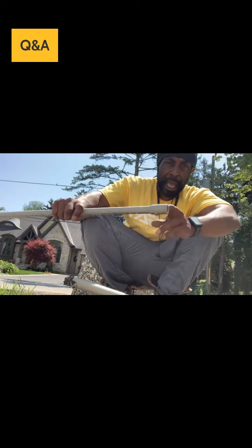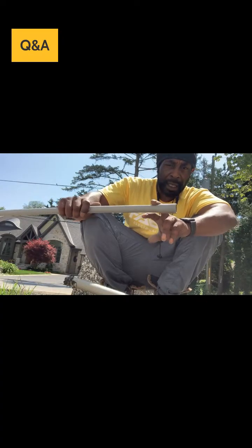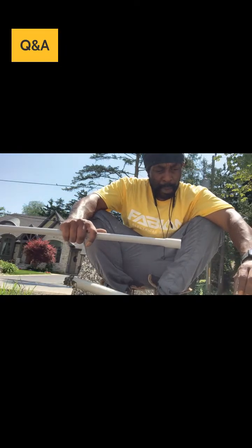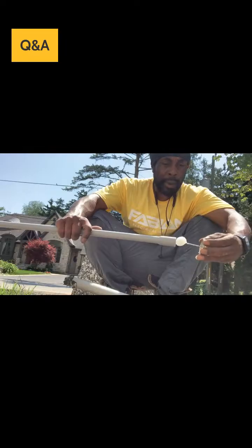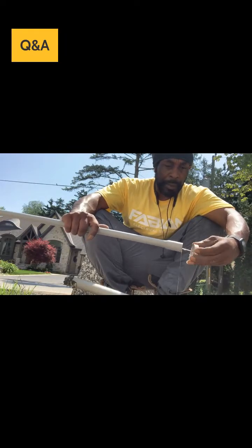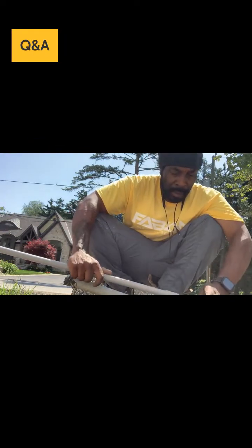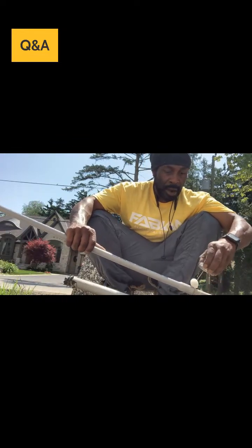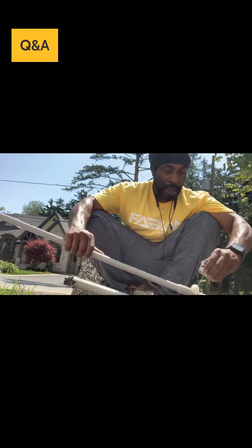This acts like a coupling, same thing. This is how they come, in 10-foot lengths. Some guys call it a bell-end, but this is what you call a 1/2 inch coupling also. Normally what I do at the end, I place glue around here, that way it's firm and secure.